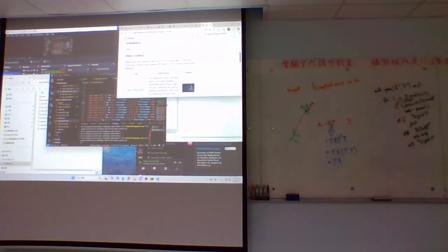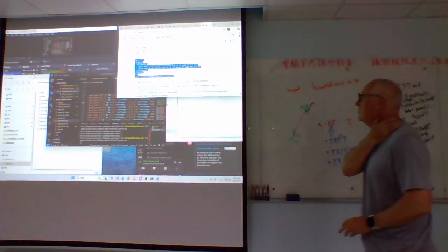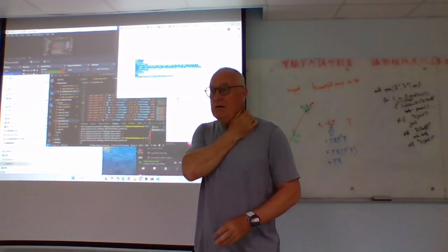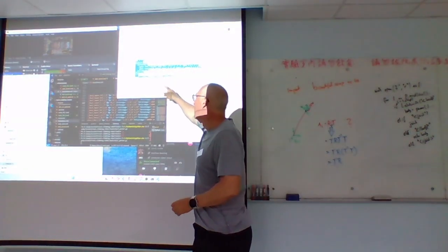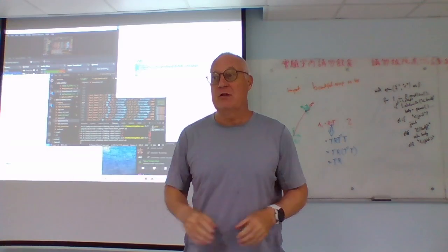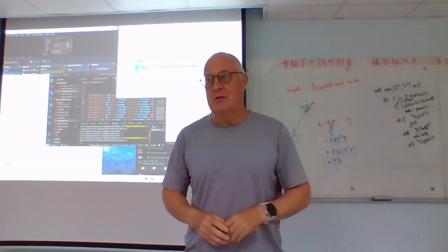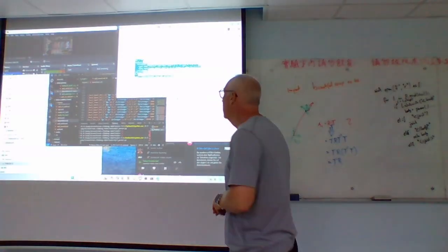There are some things you can change dynamically. Like last class, I showed the color. You can change the color of things because that doesn't impact the physics. So that's okay. The way that you usually do it is you define your XML file in your Python program, and then you call MuJoCo model from XML string. At that point, it generates the simulation environment. But before you call that function in Python, you can modify this file here.